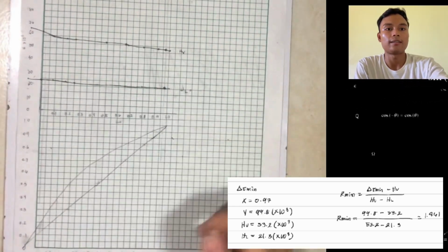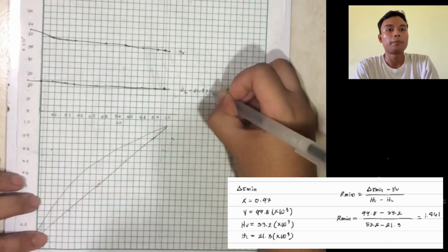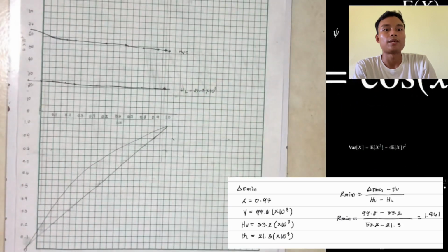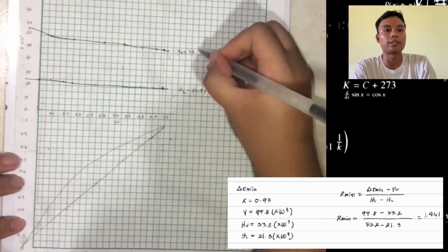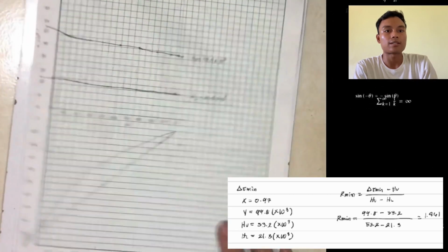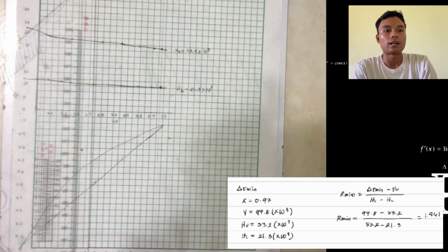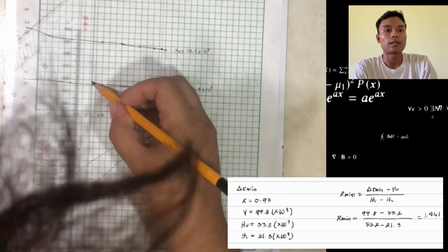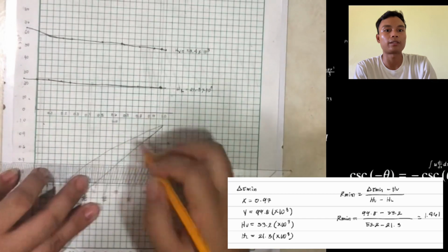So since it is said that the feed is in the saturated liquid, we will create a point given the mole fraction 0.42 on the saturated liquid line and then create a line downward till it reaches the XY diagram, and then create a horizontal line till it reaches the 45 degree line in the XY diagram and a vertical line upward to the saturated vapor line.